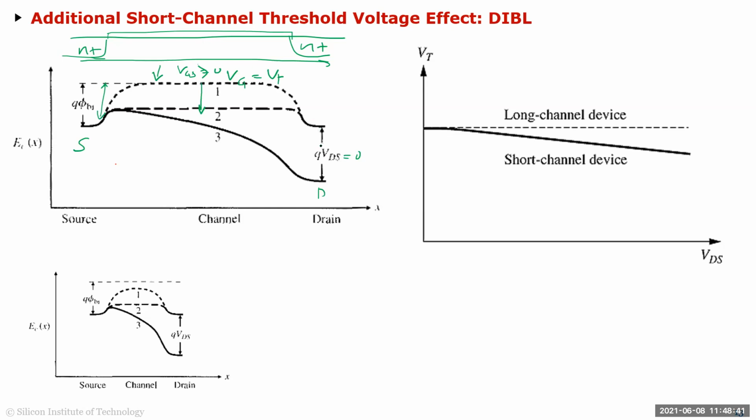Now, when you apply a drain voltage on top of it, this barrier comes down even further, and that's how you get the conduction. Because of this potential slope, your dphi over dy gives you the electric field, E equals minus dphi over dy, and mu times electric field is the velocity of the electron, and so on. We did all this calculation. That's why you get the conduction of the electron.